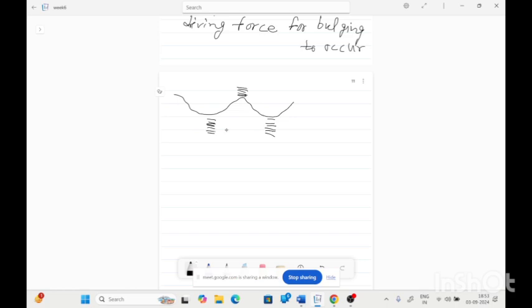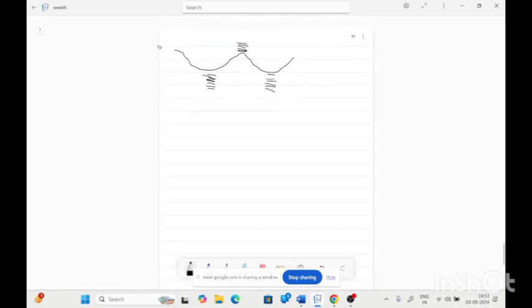So the serration formed near the subgrains are called the subgrain boundaries, and if twin forms near the subgrains, then twin boundary will be there. So the formation of this subgrain boundary is due to the rearrangement of dislocations. Means dislocation rearrange at this position, means near the subgrains.